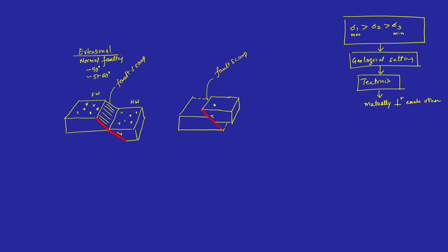And as we have been talking about, in the reverse faulting environment the hanging wall will move up with respect to the footwall. So this is your hanging wall and this is your footwall. Then finally we have strike slip faulting. For example, we have a block, again in 3D, with a sort of movement where one block has moved away with respect to another one.